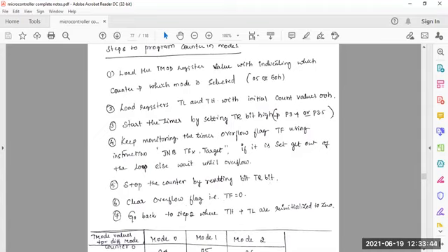Then clear TF, that is CLR TF0. Then go back to step 2 by loading the TH and TL values again with 00H. Again we start counting from 0000 up to FFFF.